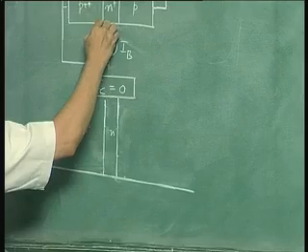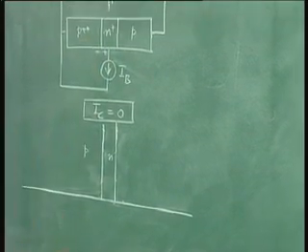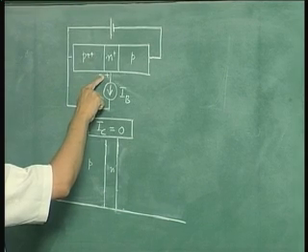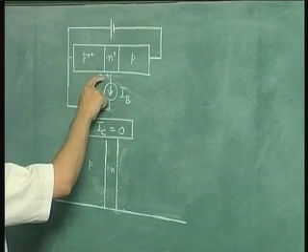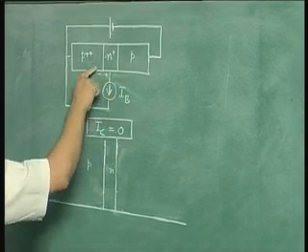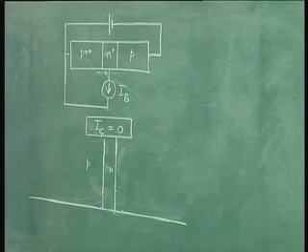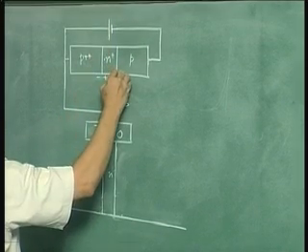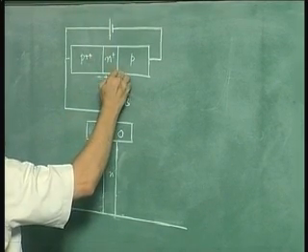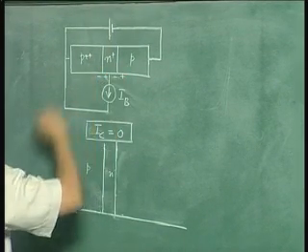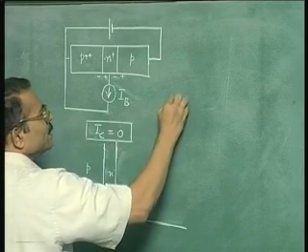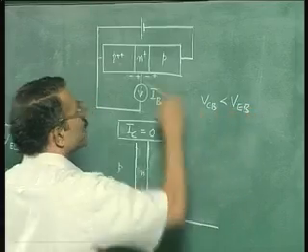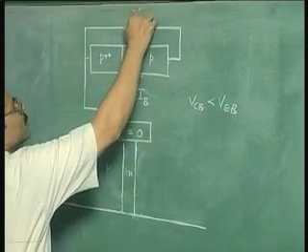Now what happens? This is forward biased. This has to remain forward biased, although its value of the forward bias may change, because the current is outward here. So there has to be a current in this direction. So when you apply a voltage in this direction, this forward bias will start reducing. Okay? So now your condition is VCB is less than VEB, as you start increasing your VEC. This is VEC.